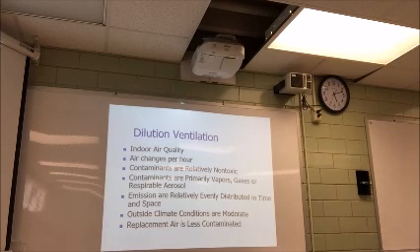Yeah, right now we've got dilution coming into this room. What happens if there's a powder or a chemical or something here? What's the ventilation going to do? Yeah, just spread it all out. Why would we only want to use it on relatively non-toxic? What are we doing with that? Yeah, we're sending it out. Everybody gets some of it instead of controlling it right in place. That's an important part too.